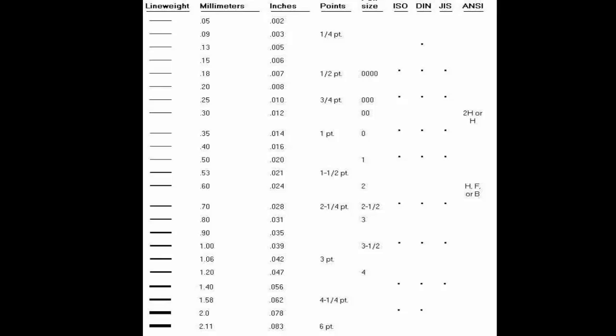If things show up on the plane of projection but they're kind of in the background, we would make those lines thinner. If we're talking about dimensions or notes, things that are important on the drawing but not necessarily the highlight, we would show those later. So our drawings become much more professional looking. We're not just slapping lines on. We actually have a reason to put our lines on in a certain line weight, in a darkness.